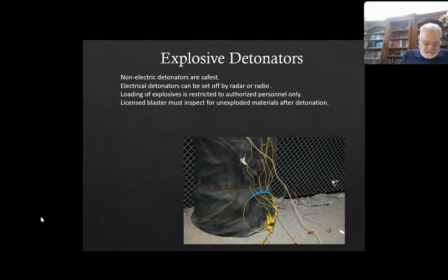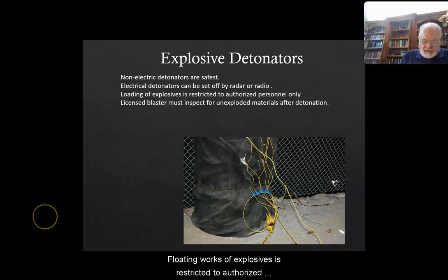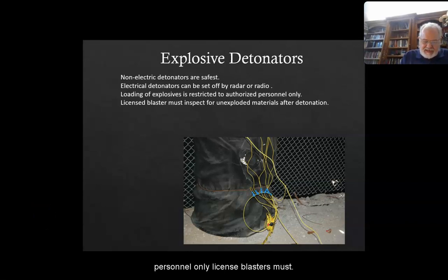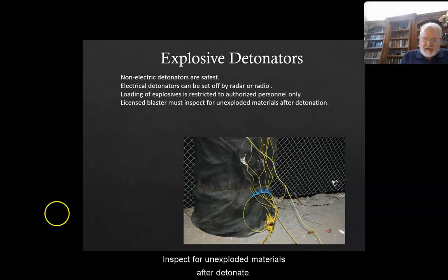Explosive detonators: this is a picture of non-electric firing systems connected to explosives wrapped around a column. Non-electric detonators are the safest. Electronic detonators can be set off by radar or radio. Loading of explosives is restricted to authorized personnel only. Licensed blasters must inspect for unexploded materials after detonation.